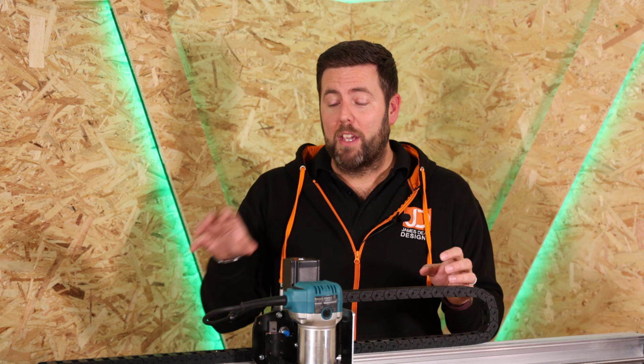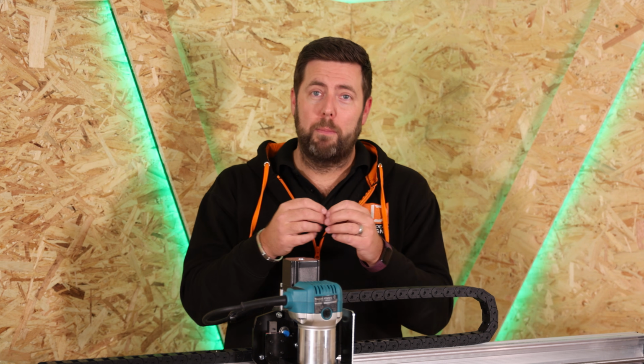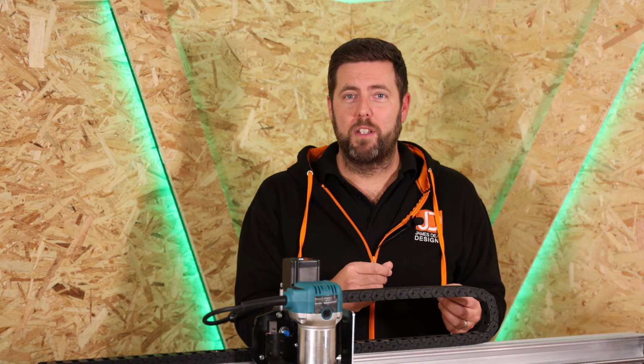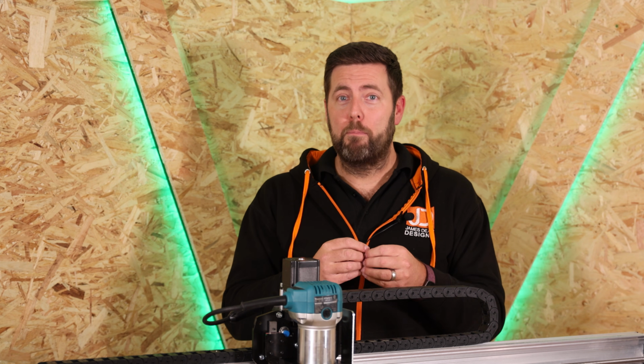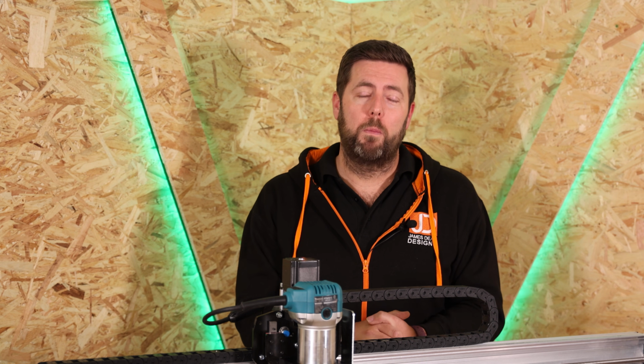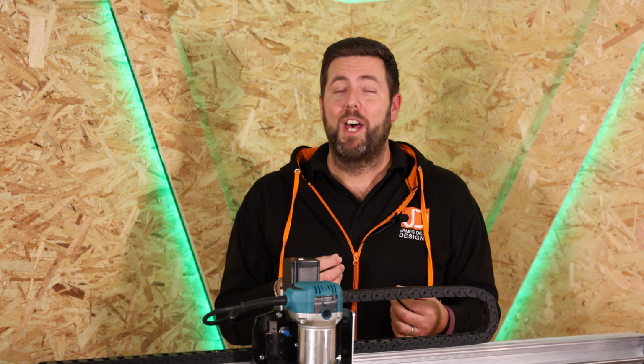Now, don't get me wrong. If you're working through that process that I just mentioned, you should see a difference in the size of the chips themselves, and ultimately you want a good quality chip or a bigger chip than something like pure fine dust. So the scale is still applicable no matter what size the machine is, but almost the size of the chip is relevant to the machine that you are using. And if you're not getting a big good quality chip like you sometimes see others producing, well, it is probably because of the size of your machine and the spindle that you are using. It doesn't mean that it is wrong. As I say, it's all about the relevance of your machine with that bit, as opposed to trying to compare it to others with bigger or different machines.